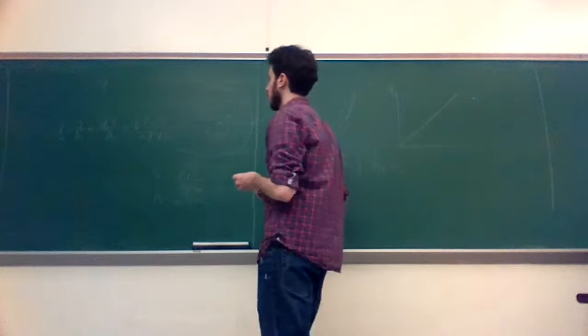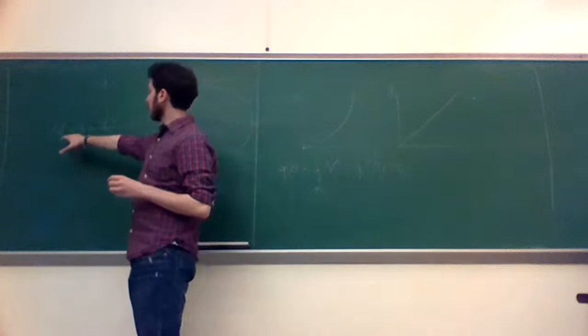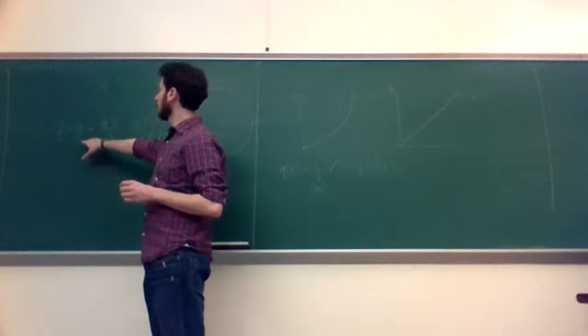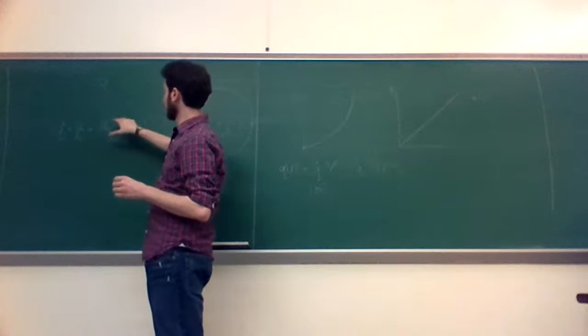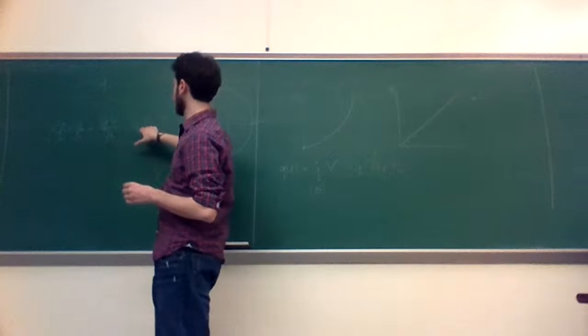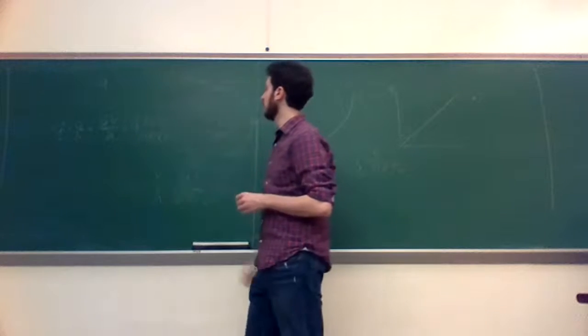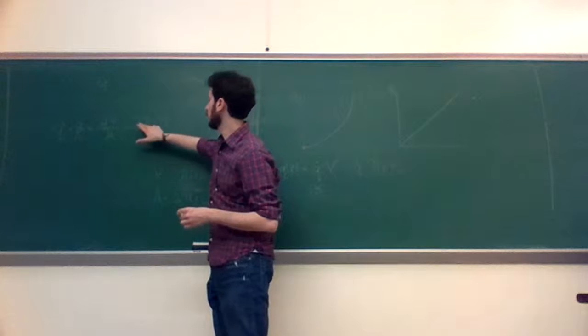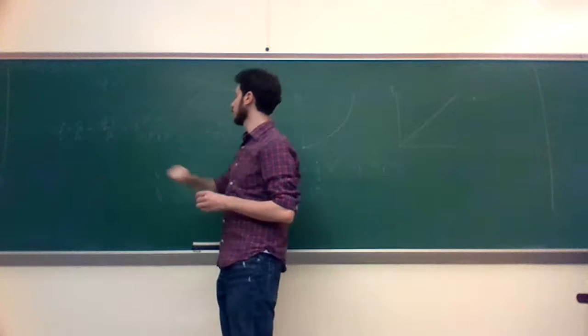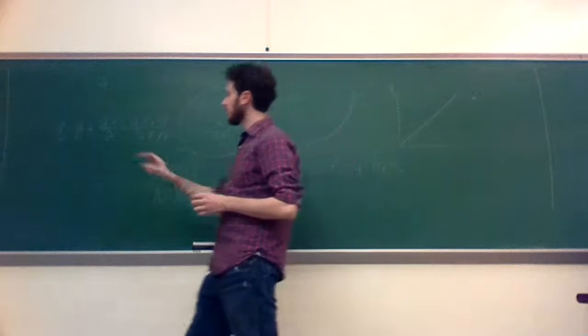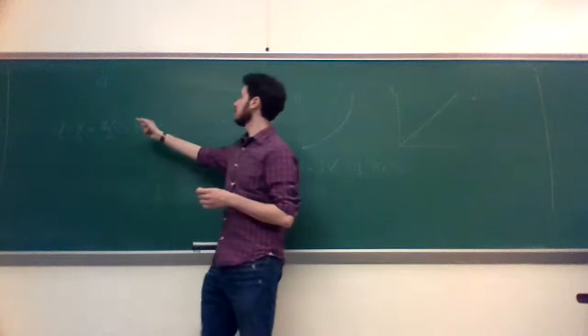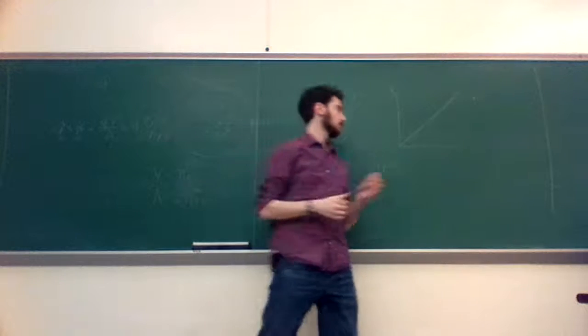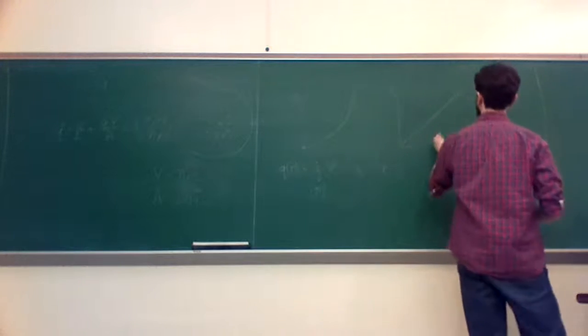Okay. So if we're interested in heat flux, Q over A, that's Q dot times V over A, and you can expand out those terms and then cancel. And what you end up with is Q dot times r over 2. So basically your heat flux increases linearly with r. This gives you your second curve.